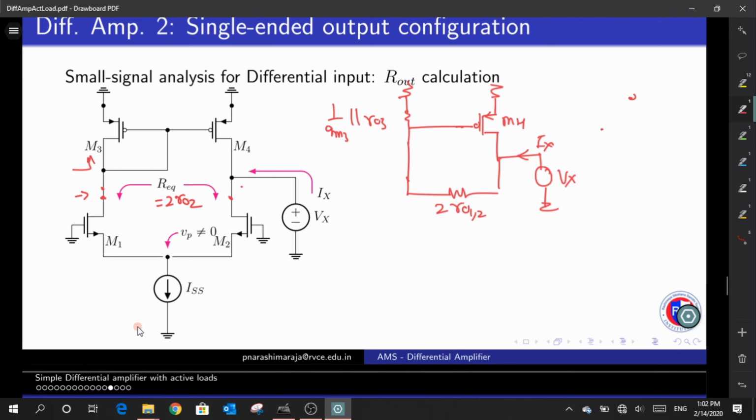I'm just going to visualize this Ix as a branch of 3 currents. Now one of the currents is through this path, path number 1. Because of this current mirroring structure, the same current would then be reflected here as well, right? On this particular node. Are you clear? So this current flow would then be reflected here through the value of VGS. So that is my second current. There is also one more current. What is that current?